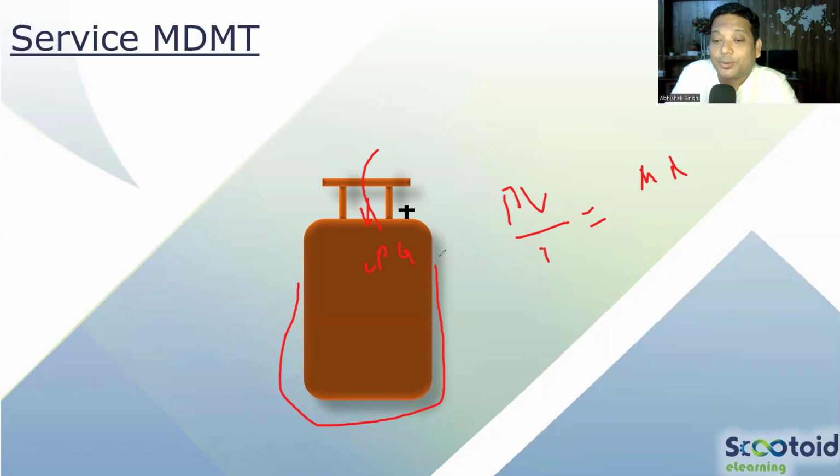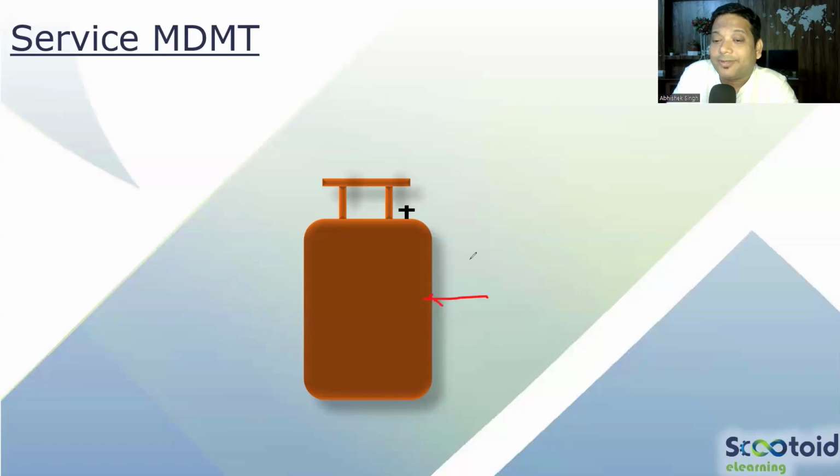The temperature is dropping very quickly, and you might notice ice forming around this gas. If we consider an LPG cylinder, you will see the accumulation of ice. Why? Because of the cold surface, whatever vapor particles are there in the atmosphere accumulate first, and then because of the very low temperature, they form ice. So that is depressurization.